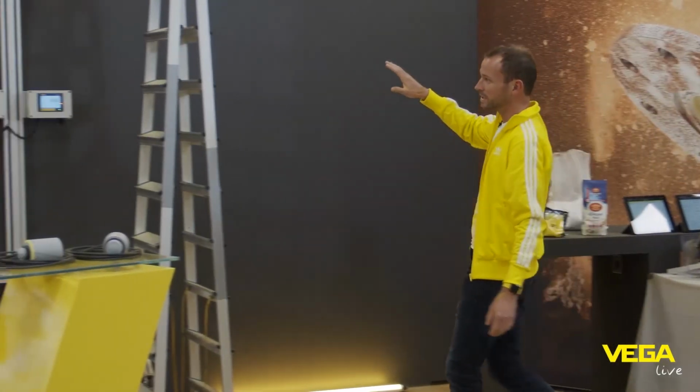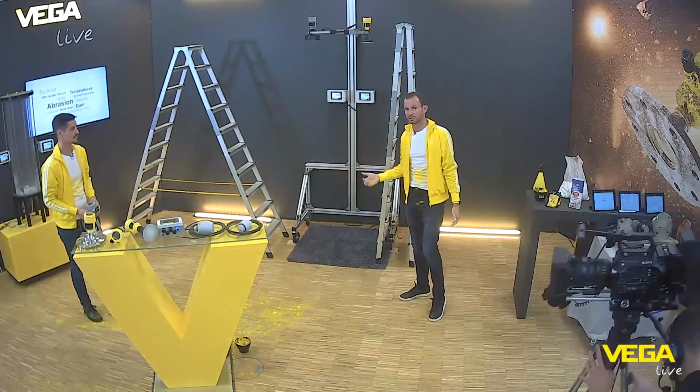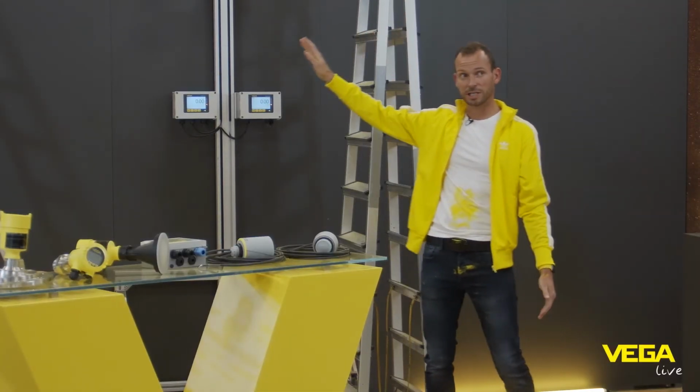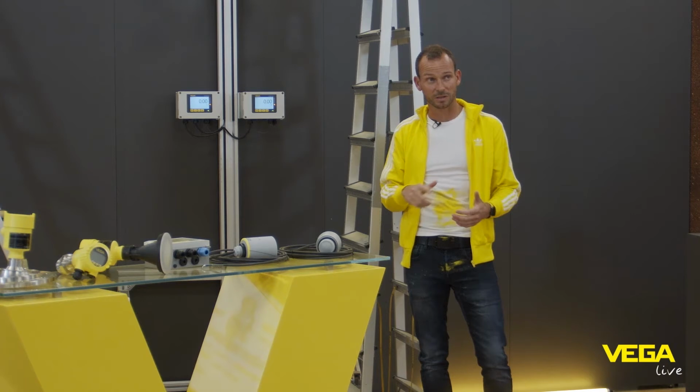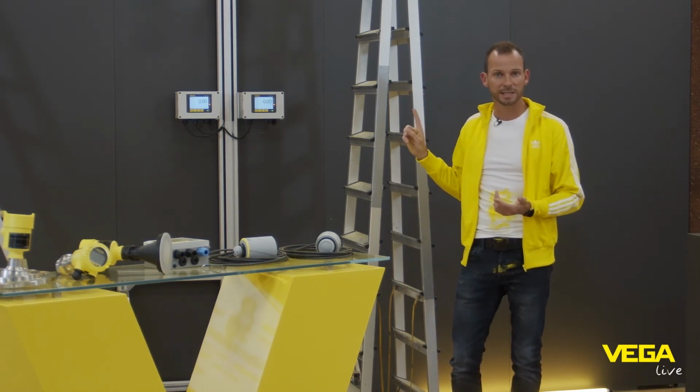Over here, you see how the letters are standing. This is the difference in focusing if you compare radar with ultrasonic. So it's easier to install and it's much more reliable in the measurement. So also here, radar is the better ultrasonic.